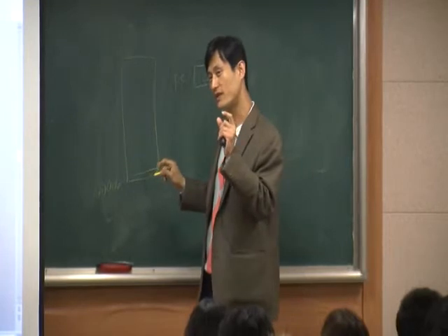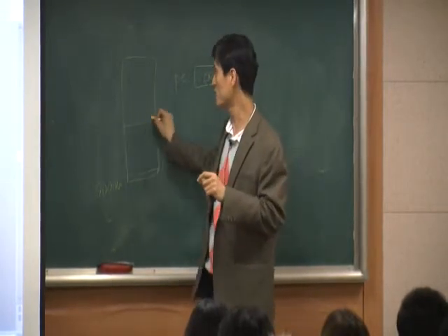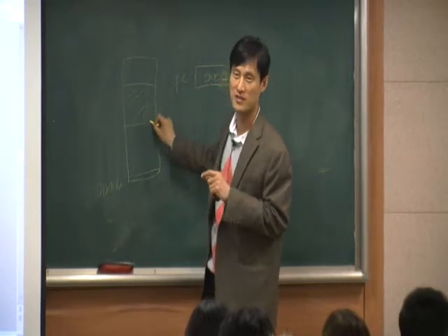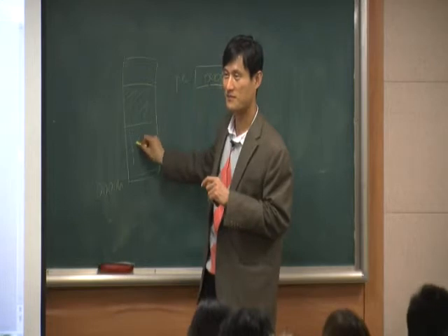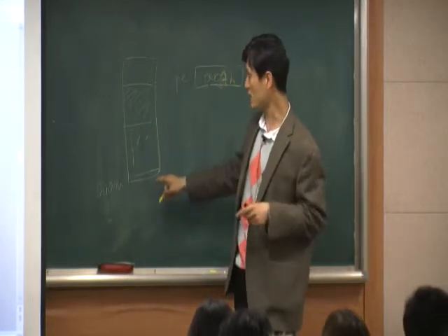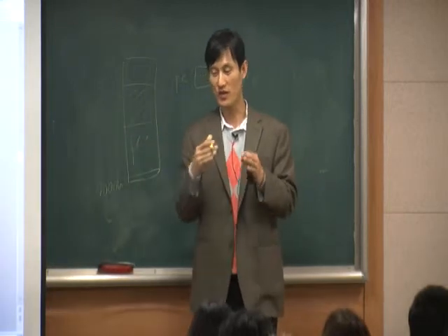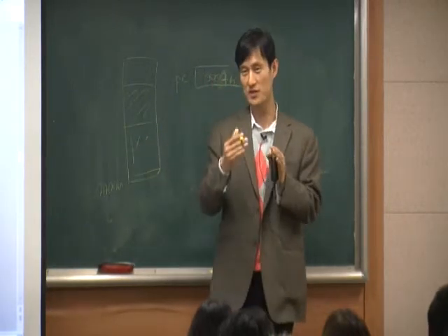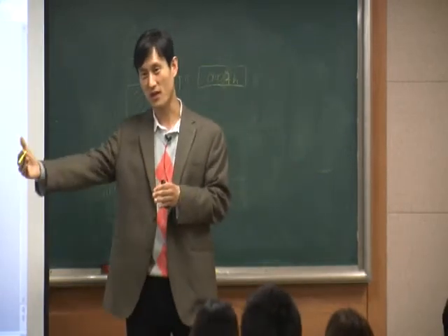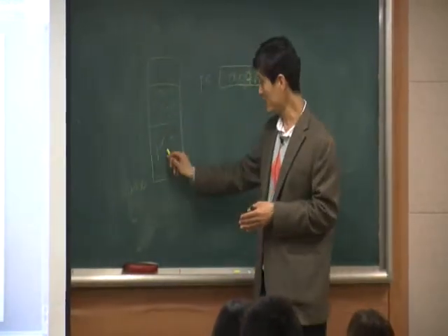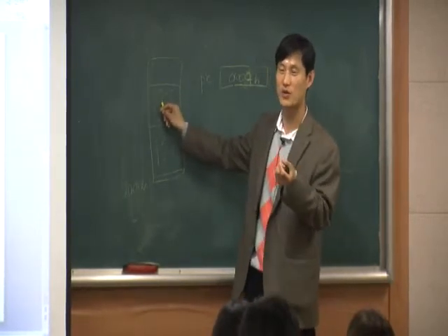But your code cannot be in here. For every microprocessor, your program is somewhere else. Your program is in here. Okay? And there's nothing in between. But your microprocessor starts from here, and the address is always incrementing. If you start from 0000, then you have to move on to 1, 2, 3, something like this, right? But here, there's nothing. So how can you go there? This is where your code is.